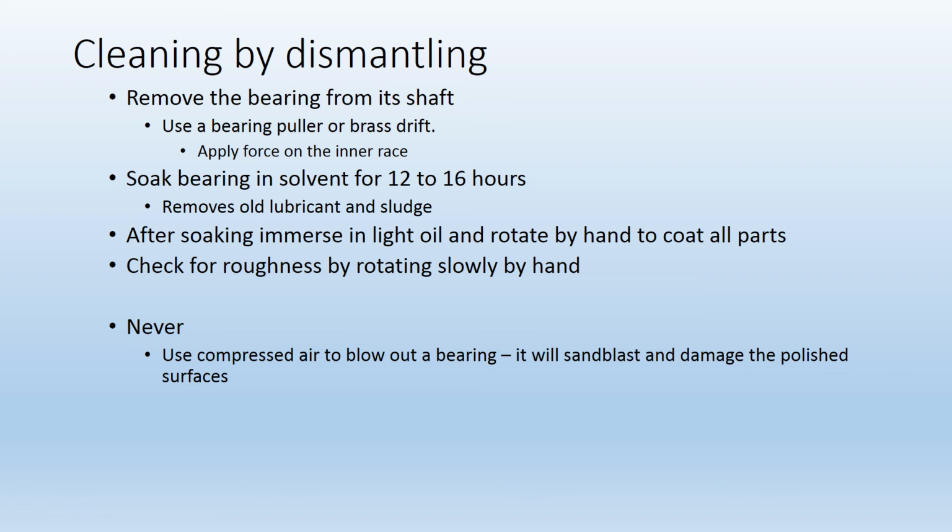So you want to remove the bearing from its shaft and use a bearing puller or a brass drift, and be very careful when you're removing a bearing and only apply a force on the races. Do not apply force onto a race so that the forces will be transmitted through the actual rolling elements of the bearing. So once you've removed your bearing, let it soak in solvent for 12 to 16 hours.